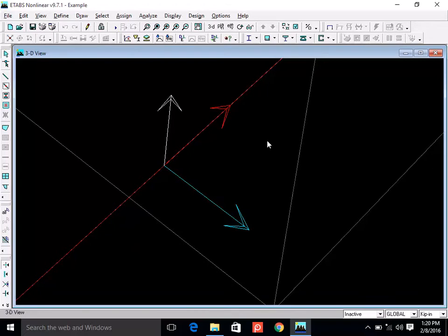In case of beams, right now I am talking about beams, although this statement is generic, vertical axis is 2. In beams, 2 is vertical. That's why you will see either white as vertical or green as vertical. Everybody confirms that? Yes, white. It means that which force is along axis 2? Shear. Because most of the time our loads are gravity loads. That's why the vertical shear is along axis 2, right?